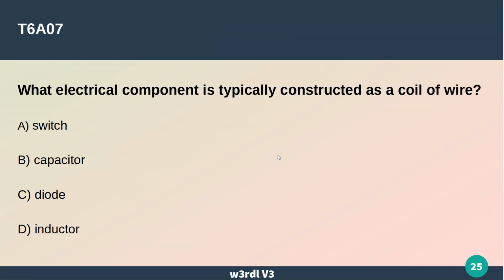Car reference. Alternator in the car has that winding. There's several of them actually. What goes bad on the alternator? The diodes are what go bad, so when they rebuild them, they're just pretty much replacing the diodes. Usually it's all on a little heat sink board, and they just replace the whole thing and charge you half as much as the alternator. Stupid money that doesn't need to be spent, but that's okay.